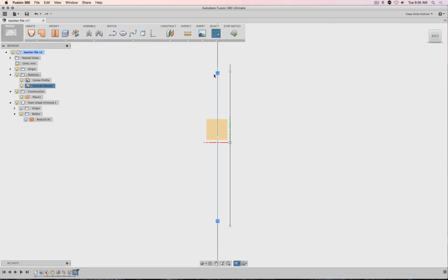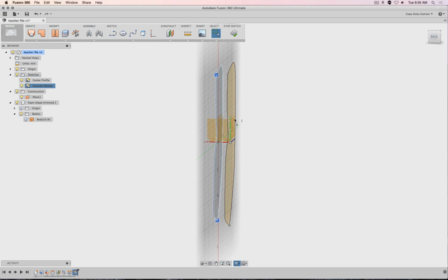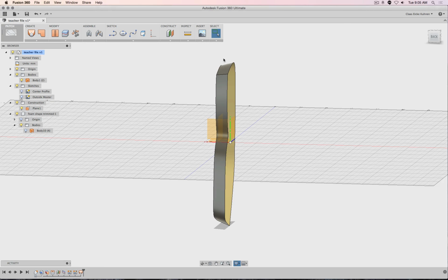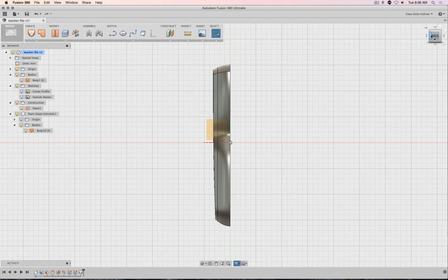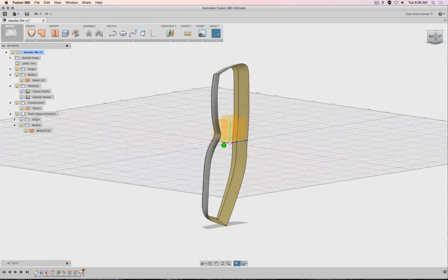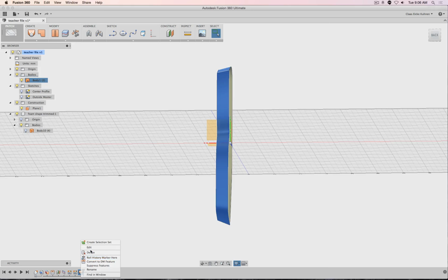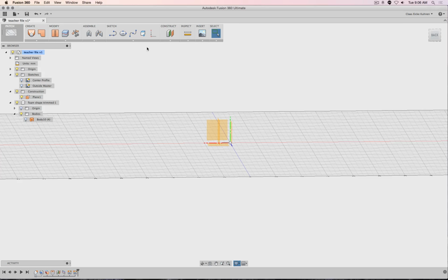Now to make a loft, I might need a third surface, because currently the problem would be, in case I would loft actually this thing together, you see it's a linear transition, but the original design is actually curved, so it doesn't really describe it correctly. So this thing doesn't work. So what I'm going to do now is make another offset from the center, but -12.